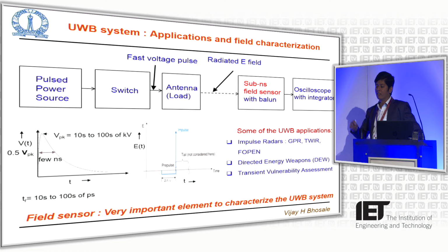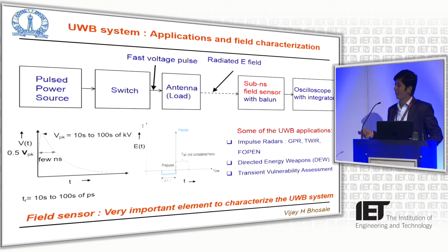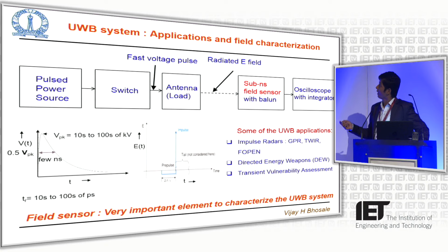This switch modeling we did using PIC code algorithms, to see how the exact breakdown happens at higher pressure levels. We played with this peaking switch up to 14 kg per centimeter square gas pressure of SF6. Also, we tried hydrogen, and next time we are planning to test this switch at 80 atmospheric pressure.